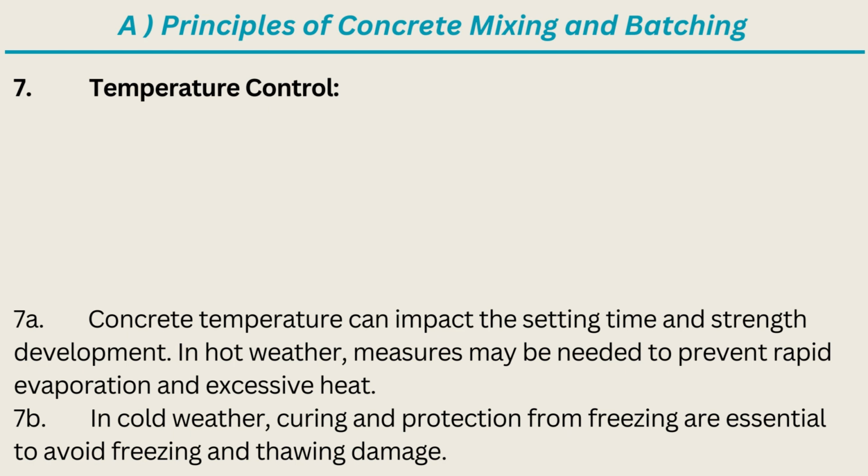7a. Concrete temperature can impact the setting time and strength development. In hot weather, measures may be needed to prevent rapid evaporation and excessive heat. 7b. In cold weather, curing and protection from freezing are essential to avoid freezing and thawing damage.